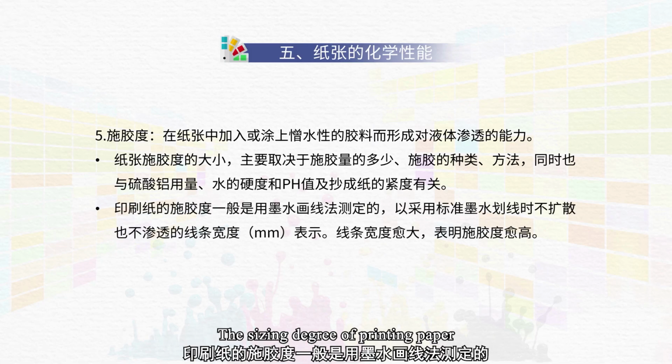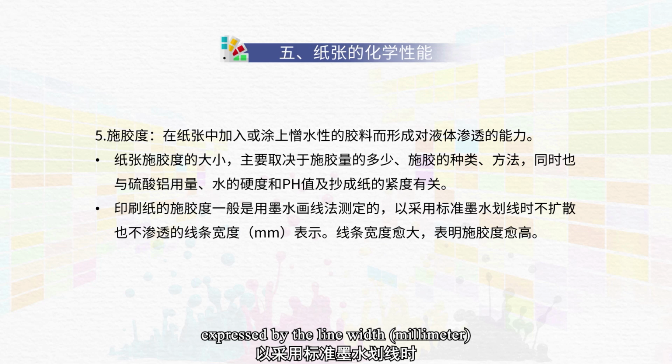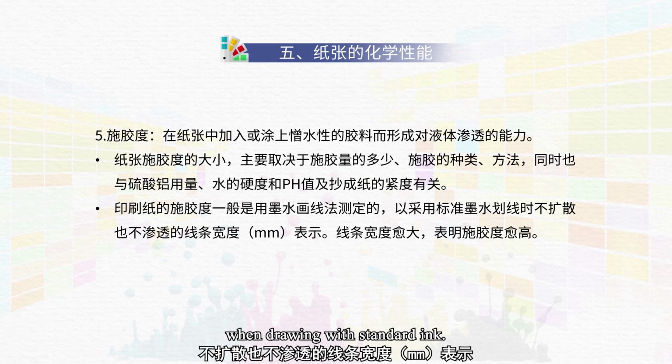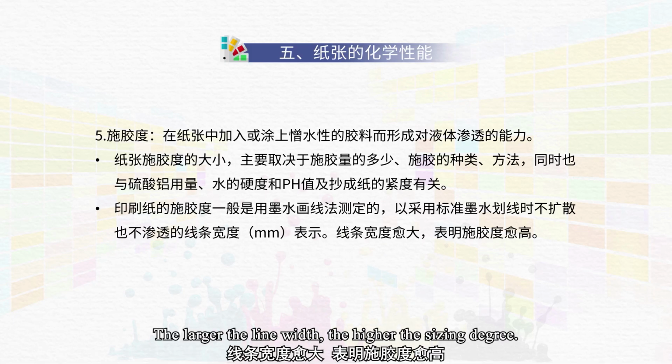The sizing degree of printing paper is generally measured by the ink line drawing method, expressed by the line width in millimeters that does not diffuse or penetrate when drawing with standard ink. The larger the line width, the higher the sizing degree.